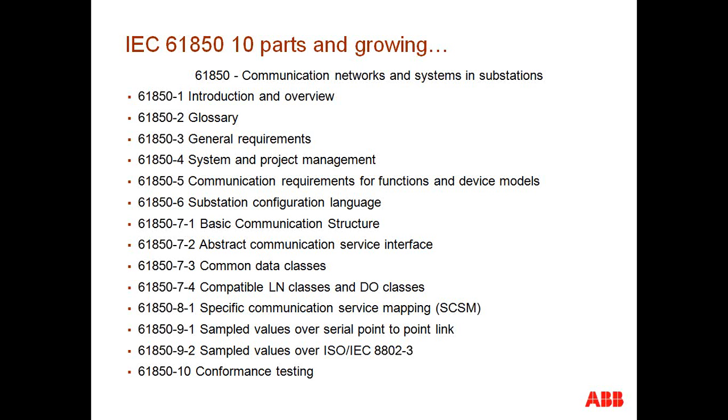Part 8-1 now really talks about communications protocols and the mapping of those logical nodes over to existing communication standards. When we refer to 61850 8-1, we're really referring to two different protocols. One is client-server, which is utilized to exchange information from IEDs over to gateways or data repositories. And the second one is the horizontal exchange of binary information.